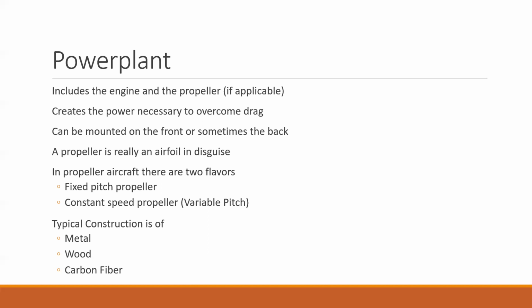And so the propeller comes in two different kinds. You have the standard fixed pitch propeller, which is basically engineered with a certain pitch along the blade. Usually it changes as it goes from the root outwards towards the tip. And it's engineered usually for a very specific airspeed.